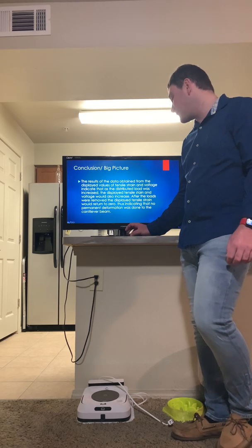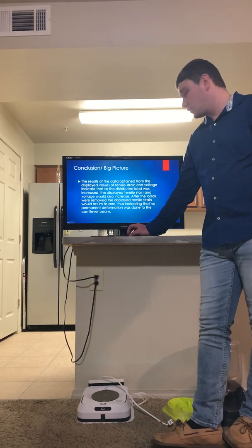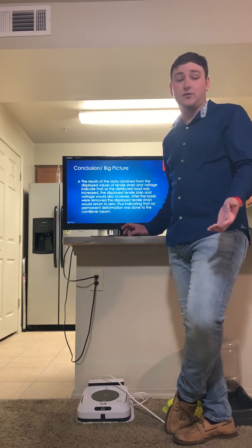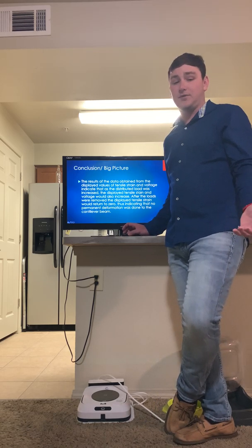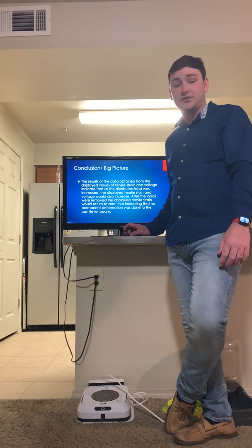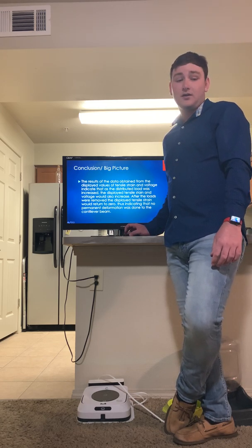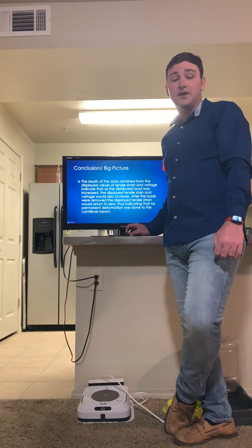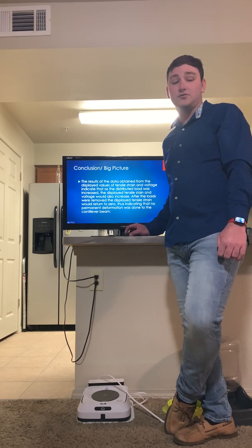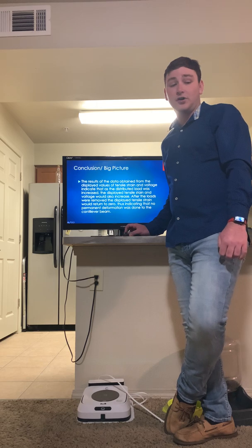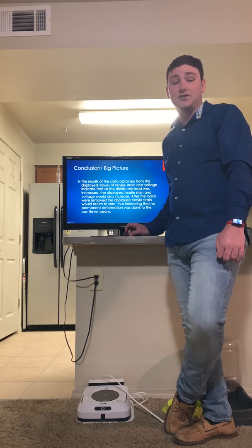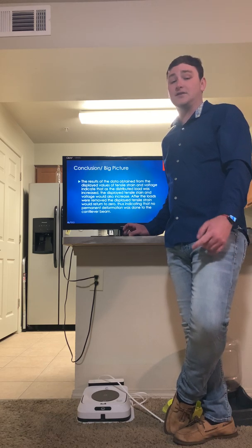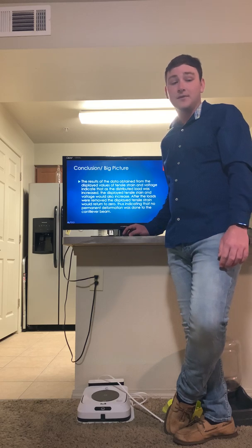So this is kind of what we found out. What I wanted to explain from all that was that the hand calculations align with the shear force and bending moment diagrams calculated using the computer software. The results of the data obtained from the displayed values of tensile strain and voltage indicate that as the distributed load was increased, the displayed tensile strain and voltage would also increase. After the loads were removed, the displayed tensile strain would return to 0, thus indicating no permanent deformation was done to the cantilever beam. That's important in this experiment as well.